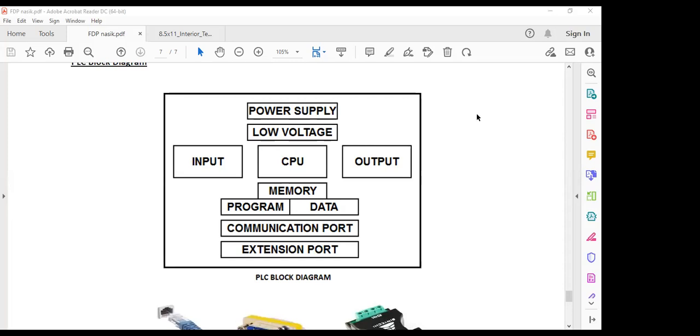So you have told transformer or any converter which converts AC to DC. That is correct. In college, we use RPS, correct? Regulated power supply. RPS you use, no? 0 to 30 volt you have there. So there you can set 24 volt DC that we can use. But in industry, we do not use such type of devices. In industry, we use SMPS. You were correct. SMPS, switch mode power supply.